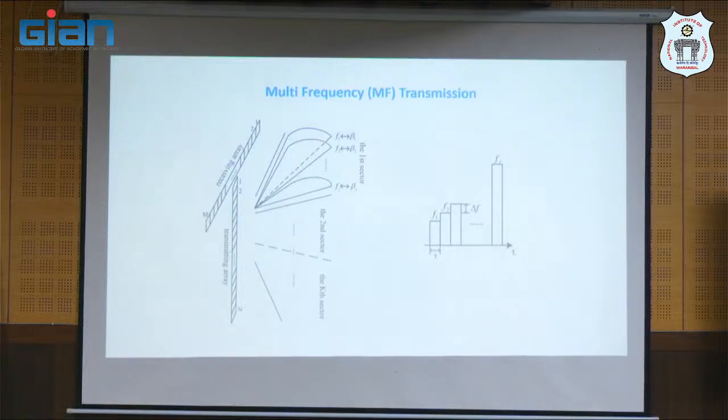Now, one more problem, the actual challenge here, as the professor also explained in yesterday's and today's lectures, is that as the frequency increases, the beam width becomes narrow and the resolution becomes better. But this is better for imaging an object above the seabed. If something is below the seabed, then the frequency should be lower, meaning the signal has to penetrate. But when the frequency becomes lower, the beam width will be higher and the resolution will be poor. So how to address this problem?